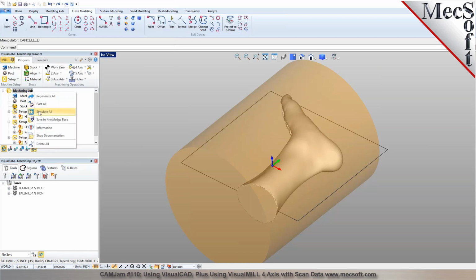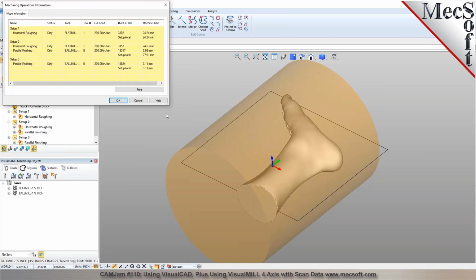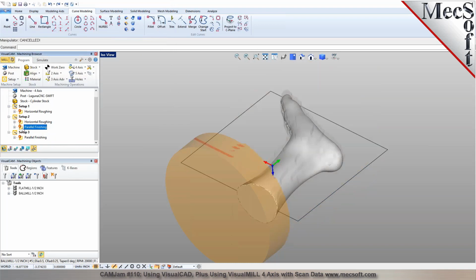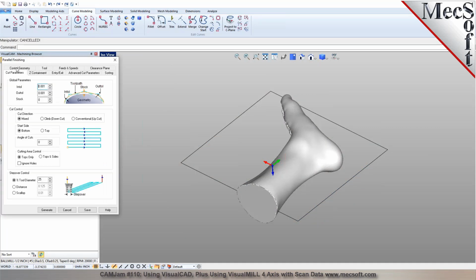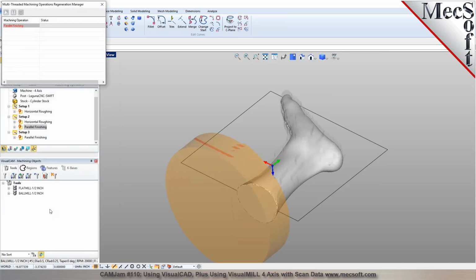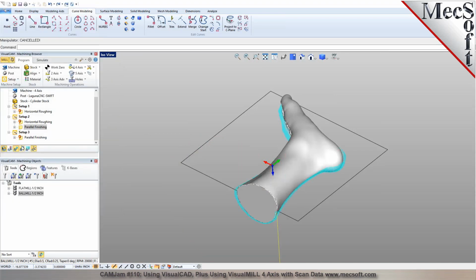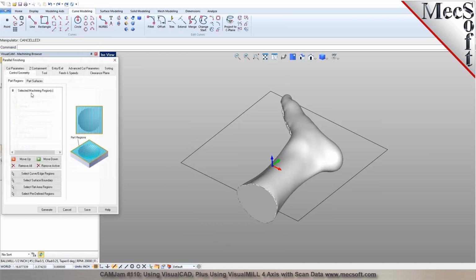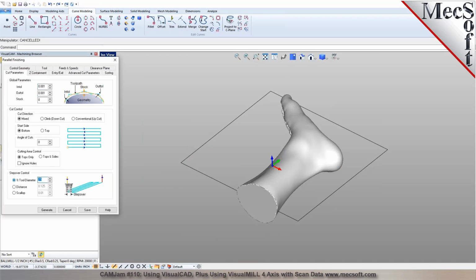With those parameters you put in. This is the step overs, right? So the tighter the step over, the smoother the finish. What do we have as our step over? Yeah, I only had the step over for finishing at 25%. I could drop it to like 10% or even 5%, depending on how fine of a finish you want to accomplish.